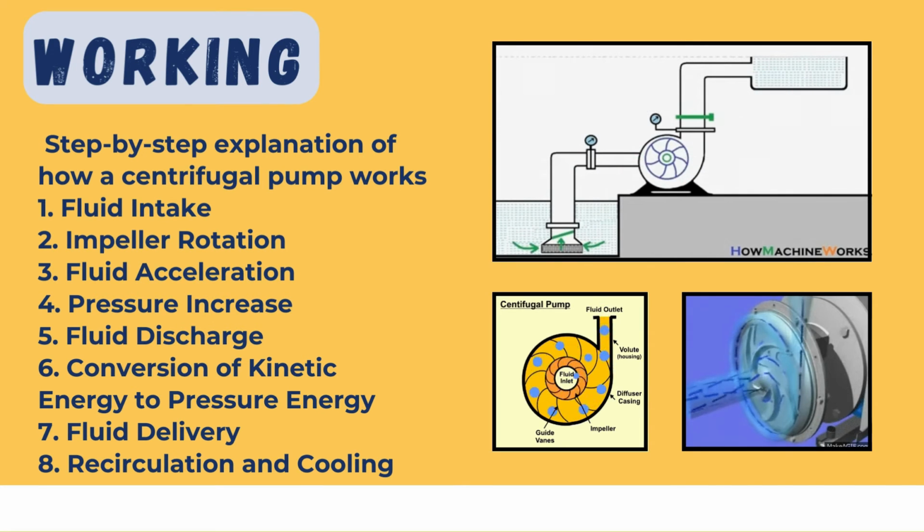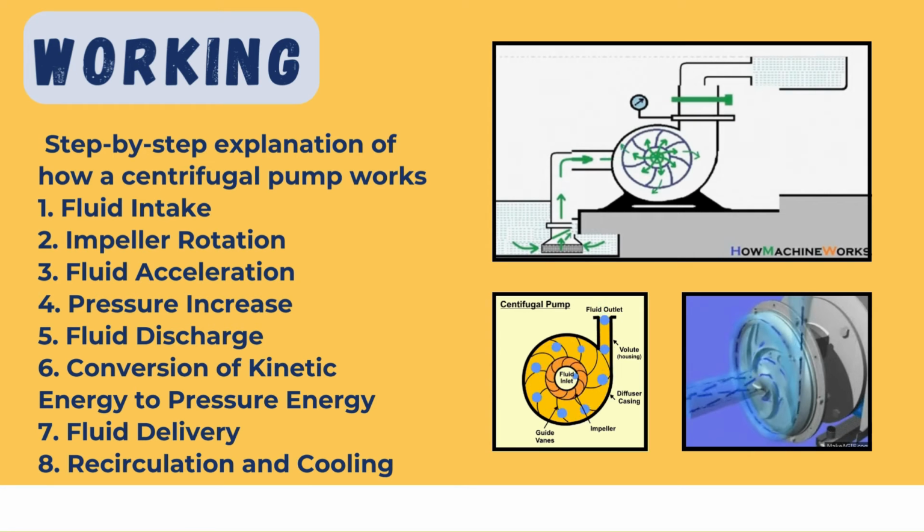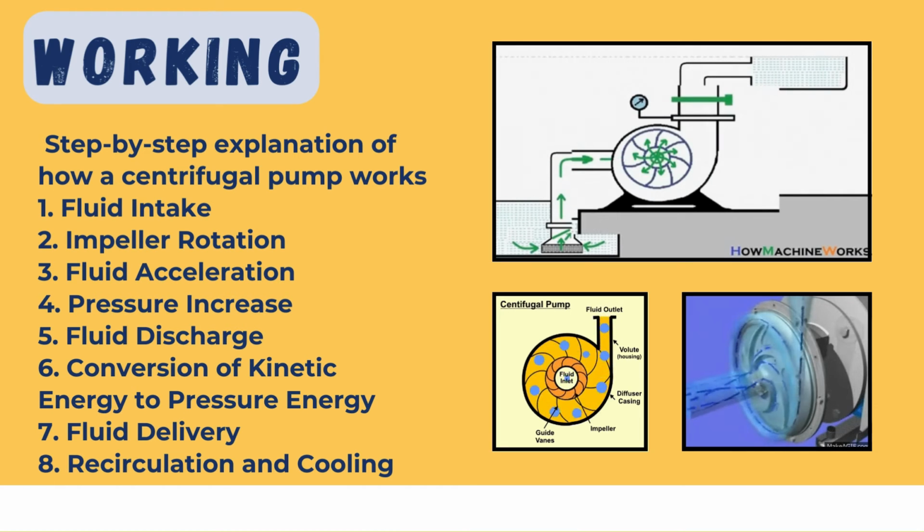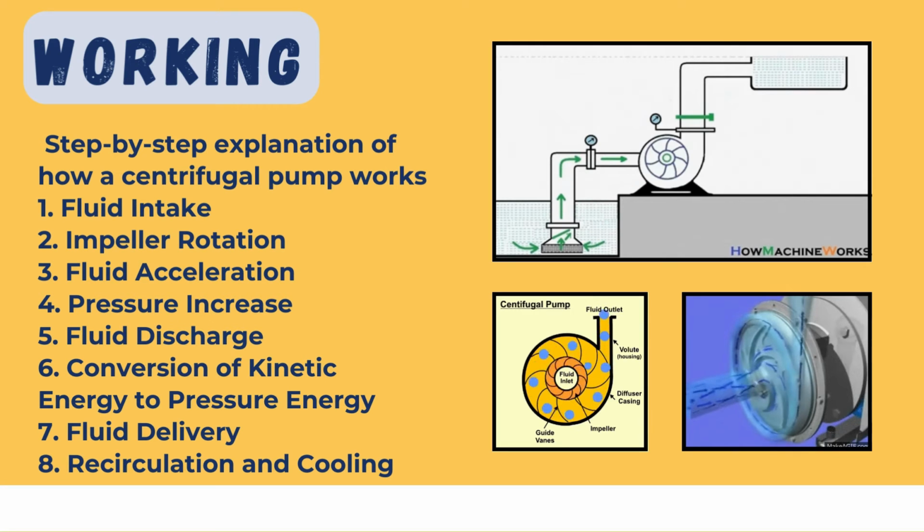Now after the fluid intake comes the impeller rotation part. Guys, the impeller, which is a rotating component with curved blades or vanes, is driven by the motor or engine via a shaft, right? And as the impeller rotates, it accelerates the fluid radially outwards due to the centrifugal force.